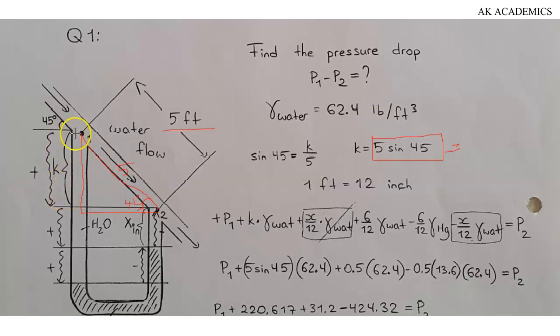And since water flowing through the manometer downward is going to give us a positive pressure, this is going to be positive. This is going to have positive notation when carrying out our analysis. Also, there will be positive notation here, because water will be trickling and flowing downwards. When we get to this particular point, the liquid in this manometer, which is our mercury, is flowing upward.